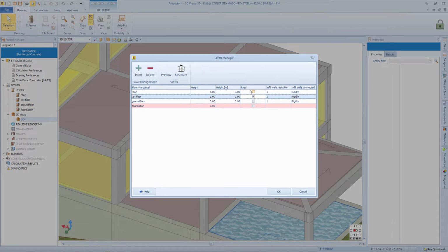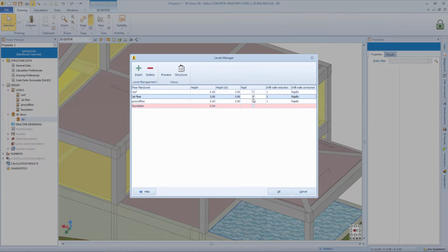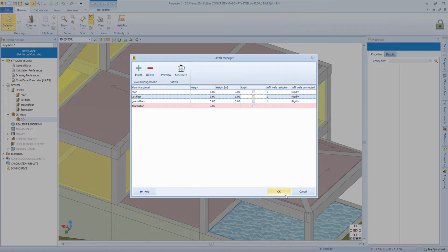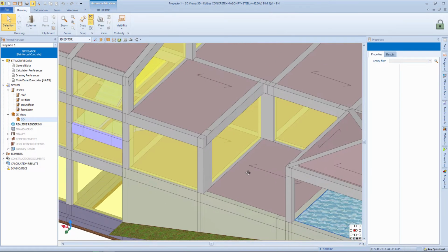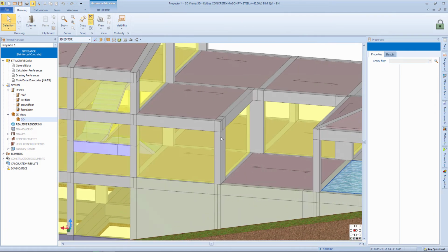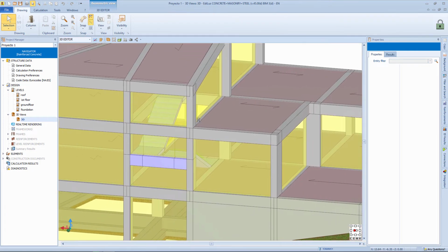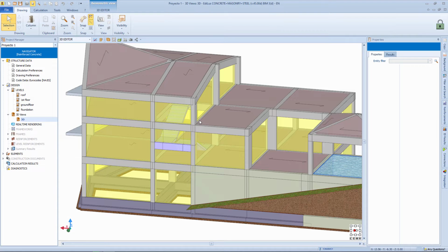By activating the field, we assume that all the slabs or panels are rigid. Then the program defines the classic kinematic relationship between the main node and the secondary nodes of the floor. This modeling hypothesis is not always the most appropriate, in which case you need to deactivate the field. Just look at a model in which we have a series of openings on a floor, such as at the stairs. So the rigid floor is not always the right solution.